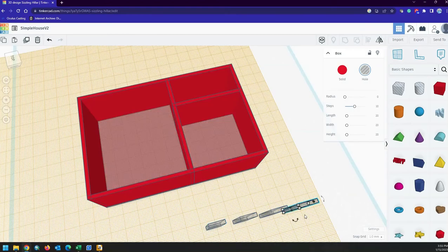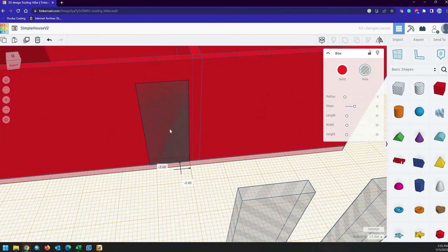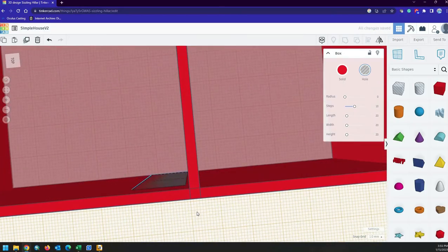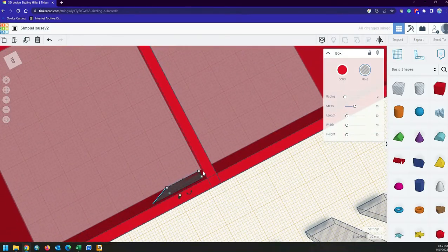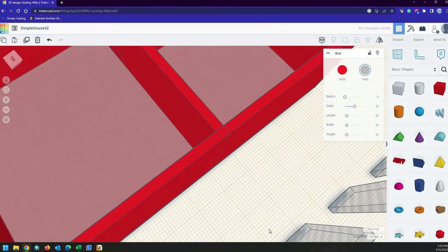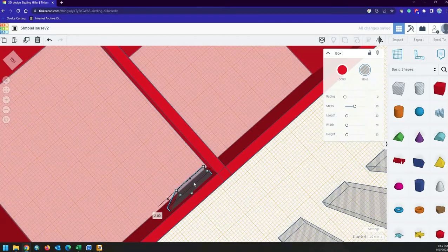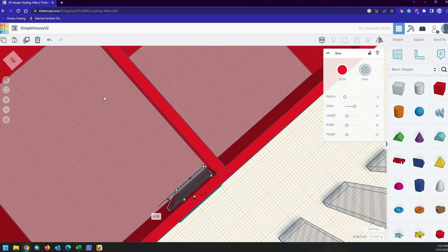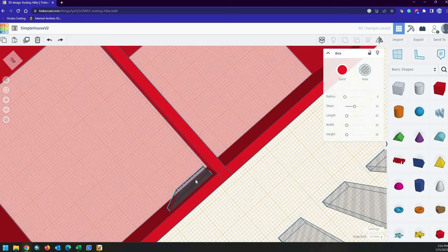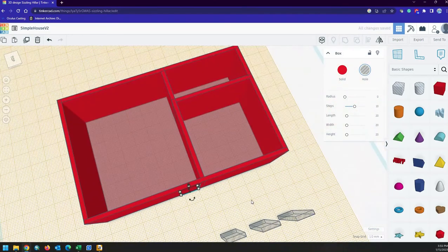Okay. So to put the front door in, I generally just kind of offset them 1 millimeter from the edge of a wall. It gives you 3 inches in theory, kind of for the return. You can see it back here. You can see the 1 dot there, but another way to help is if you pull it out a little bit, you can see the line there on the bottom, so it helps you count a little bit with that grid. Oops. Undo is your friend when you make a mistake. Alright, so there's the door. We'll cut that out in a second.